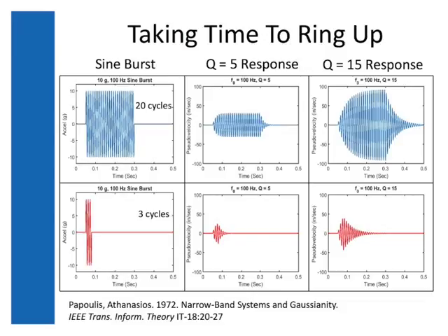This is sort of a toy kurtosis model in that I'm going to go from a low level, in this case off, to a high level, in this case a 10G sine wave, and then back to a low level, which is off. So this is sort of the simplest imaginable toy kurtosis model. In the first test, we are going to leave the sine burst on for 20 cycles at resonance.